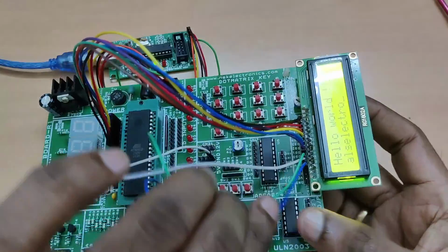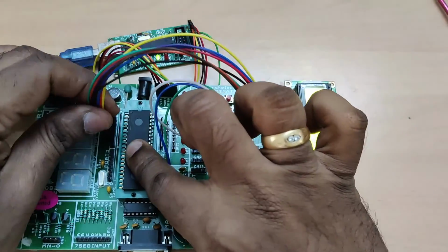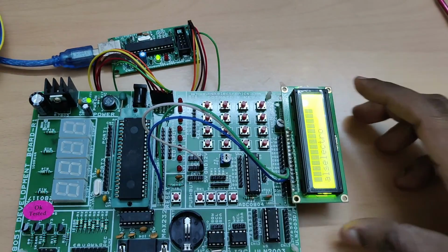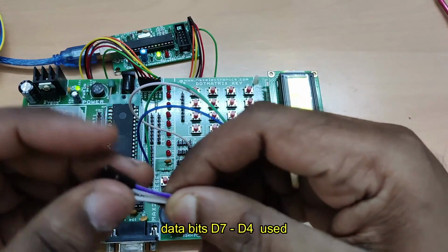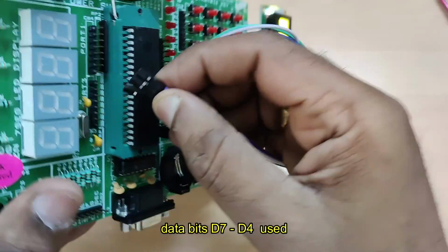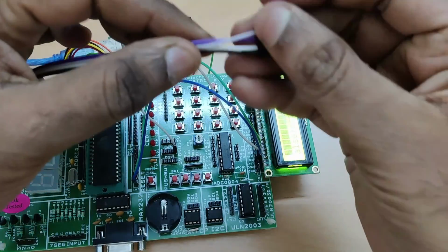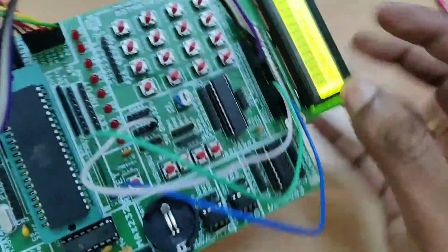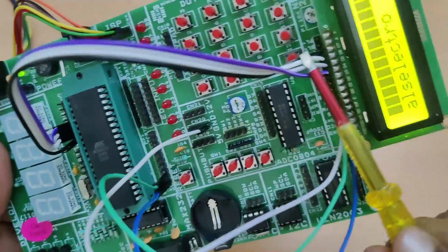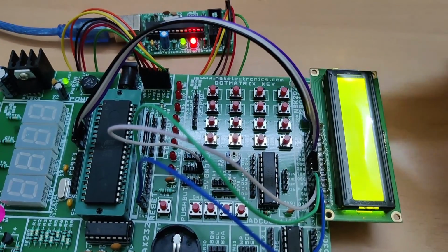Now let us do the connection. Remove the 8-bit connection from port 1. We'll be using D4 to D7 only. So the command pins will remain as they are, RW, RS and enable pins. For data bits, D4 to D7 are used. D7 goes to P1.7 and D4 goes to P1.4. So only the 4 bits are used here. And P1.0 to P1.3 is not used. The command pins are left as they are, as we used for 8-bit.